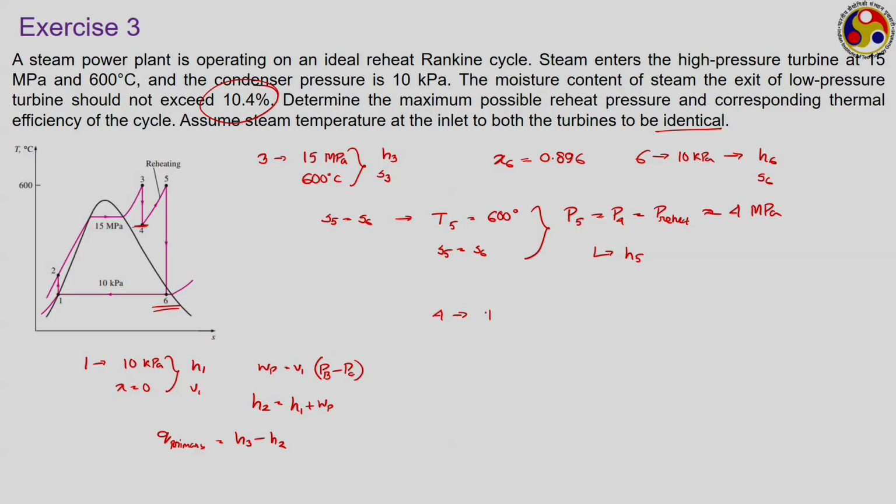that for point number 4, P4 is equal to 4 megapascal and S4 should be equal to S3. From there you can get your T4 to be coming approximately equal to 375.5 degrees Celsius. From there you can calculate H4.